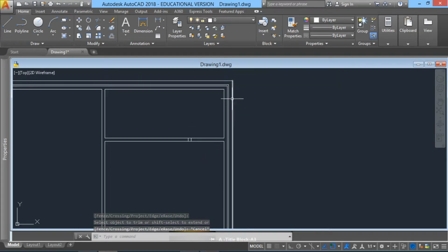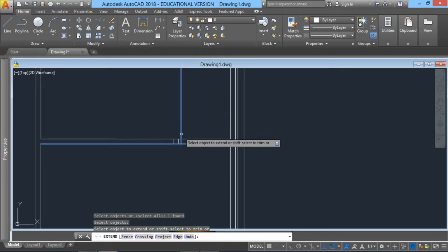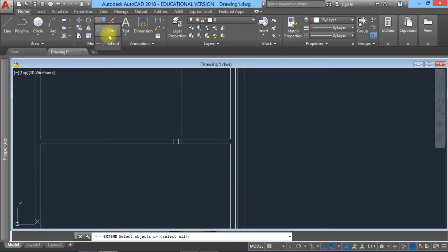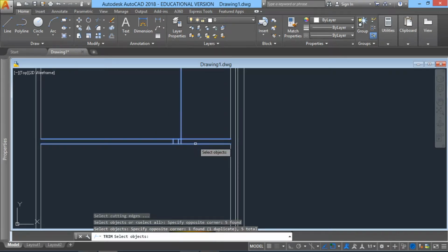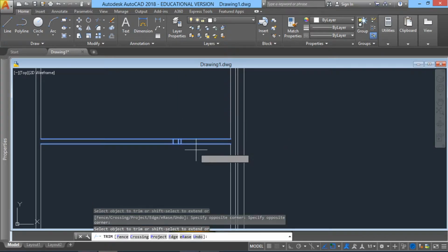The first door, I'm going to insert it in this area, and that door has about a 900 to 1100 millimeter opening. Then I offset this one, and in this case I should extend to this area and that object. Then trim that lines.